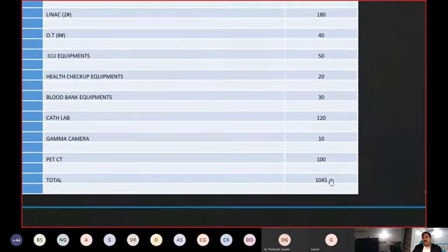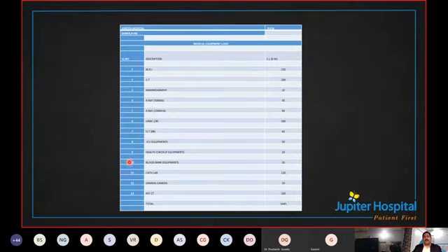So how much we have to use transformer, how much we have to use DG, don't worry at all, because all these loads are taken only whenever they are doing scanning, for that much time only, certain for a few seconds, a few minutes. Only that much load is taken. Otherwise the diversity is too much. You are saying 1045, in diversity it is less. It is coming to be around 350.